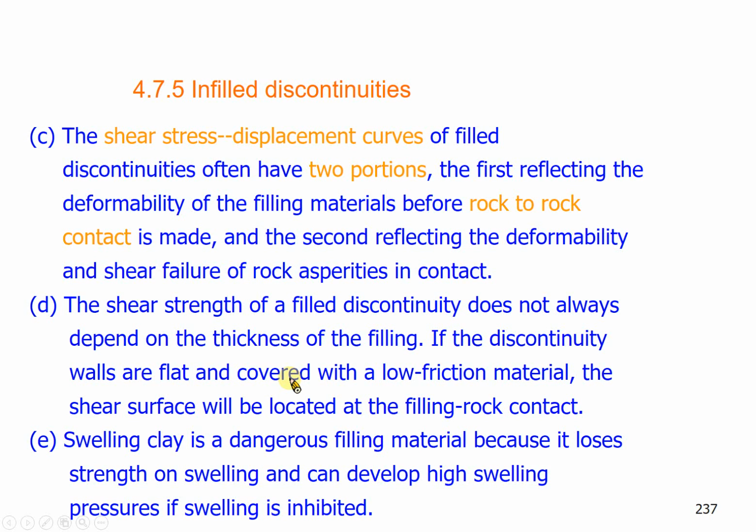Okay? Sometimes the shear strength and the stiffness of the discontinuities with infill material is not really necessary. It depends on the thickness of the infill material. Okay? Sometimes it's not. If you have very strong asperity contact, it will be not. Okay? And we always care about the so-called high swelling potential clay, like the montmorillonite.